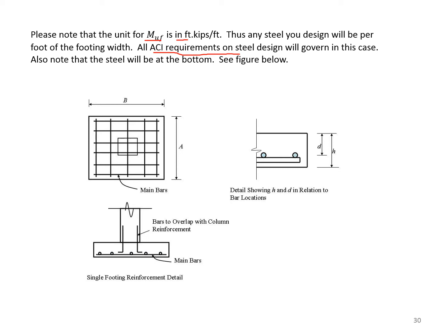There is a grid in there, the main bars. And now you realize why I insist on using D equal to H minus 3 inches plus 1.5 times the diameter of the bar. As you can see in here, the bars are like a grid. Therefore, it's a good idea to use the distance with respect to the center of the first layer of bars, just conservatively.